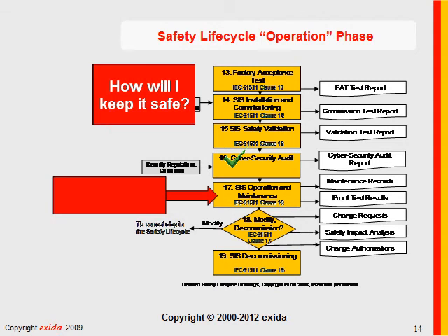We're determining how I will keep the plant safe, and in fact, we did calculations in the realization phase to determine proof test intervals. We may very well have failure rates higher than those assumed, in which case we're not getting the levels of safety that we expect.